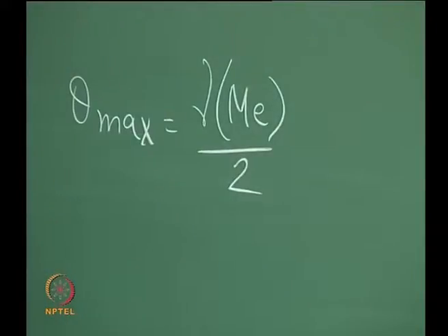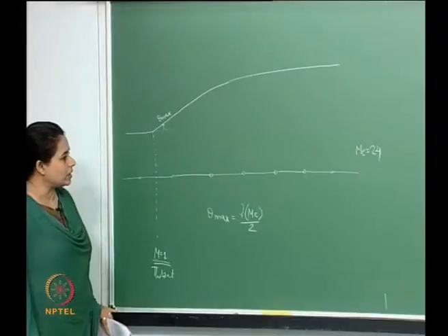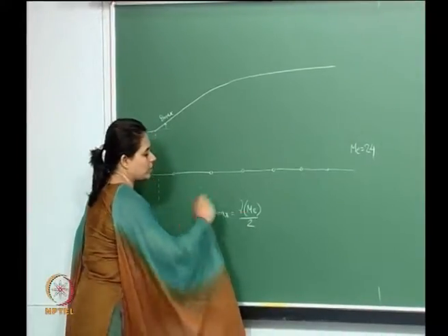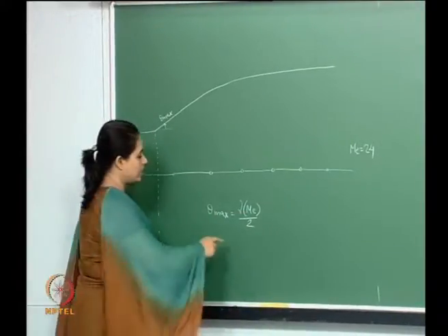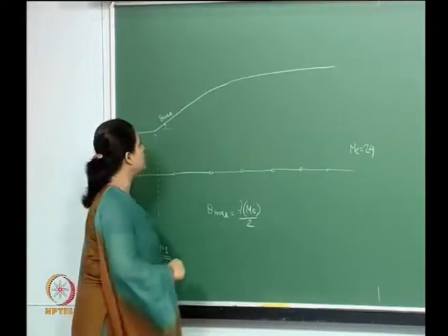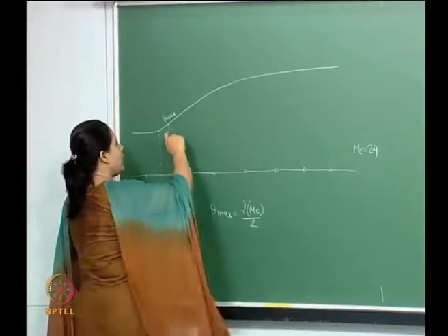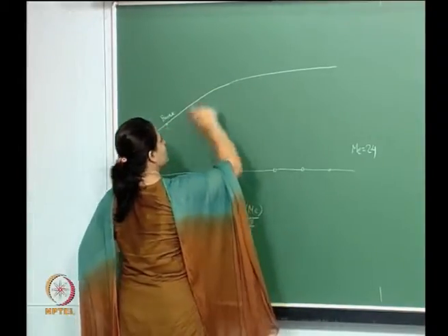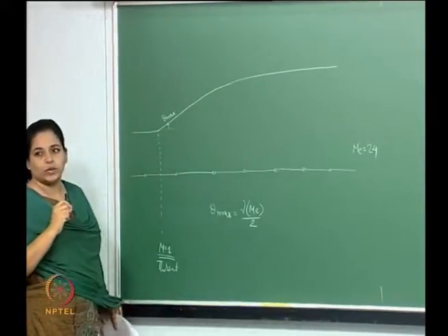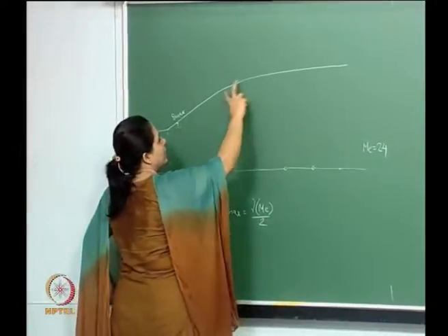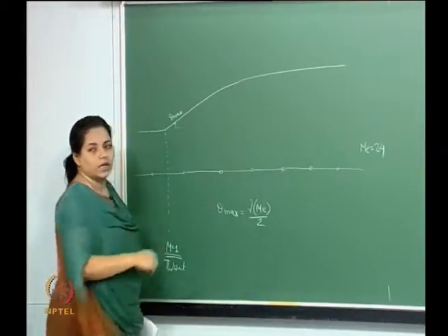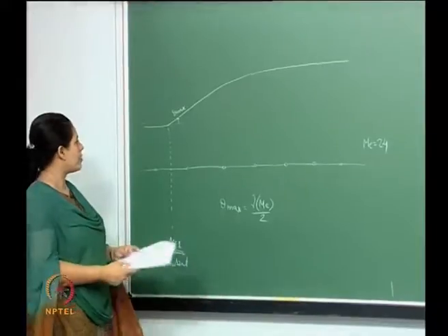the Prandtl-Meyer function with respect to the exit Mach number, half of that. So that is your theta max. That is all the information we have. What we don't have right now is this contour, and this is something that we need to design. We need to say where various points of this surface are going to be located. So that's our problem.